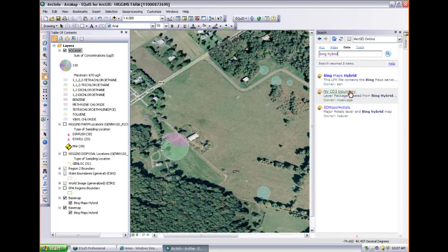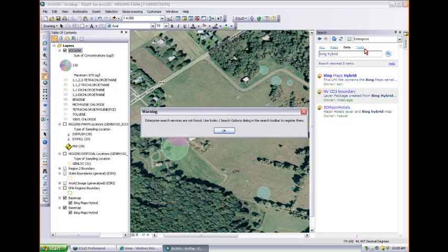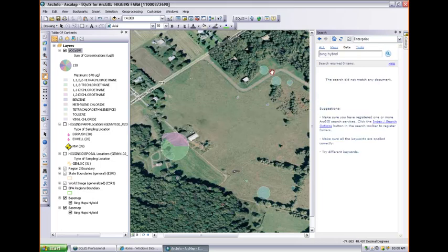It's a feature of ArcGIS 10. They basically integrated the Arc catalog and geoprocessing into these different tools. So the trick is to bring up the search and then change the drop-down from local search to ArcGIS Online. You can set up enterprise search and have it set to index, if you've got geodatabases on your network. You'll definitely want to set this up when you all migrate to 10 to index all your geodatabases, because it's really fast at searching. You want to do it overnight because it can be kind of a hog.